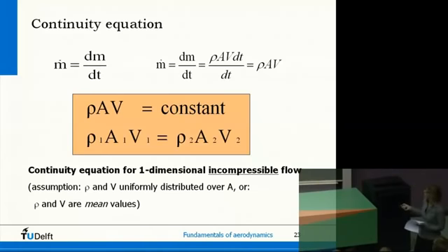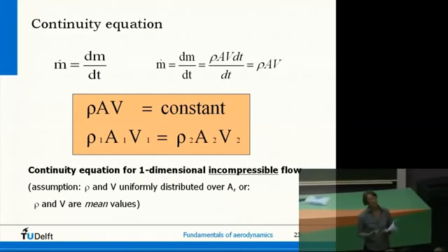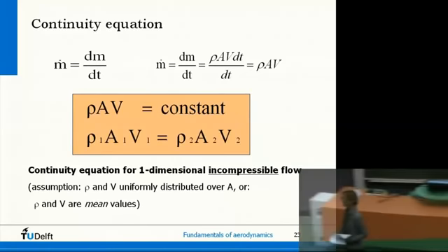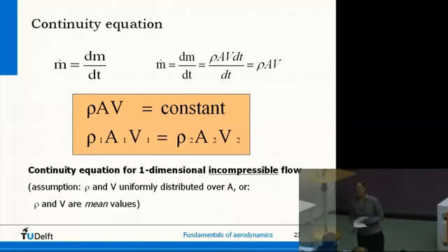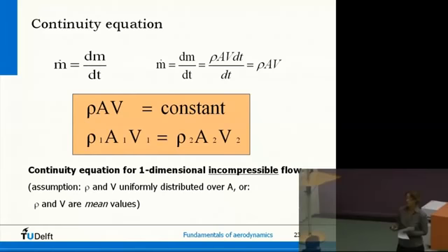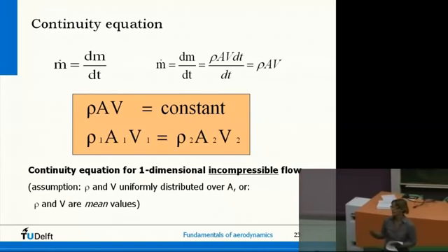However, for incompressible flows, and incompressible flows don't really exist, they are an assumption. And the assumption is the density doesn't change significantly. When is this assumption valid? When you have liquids, yes. Liquids, oil, water, we don't have much density changes, right? In a gas, you can compress it, and you can get the molecules closer, and you get strong density changes. Liquid and oil, it's much harder. However, with air, you can also have the incompressible flow assumption making sense. For what type of air flows can you assume incompressible flow?